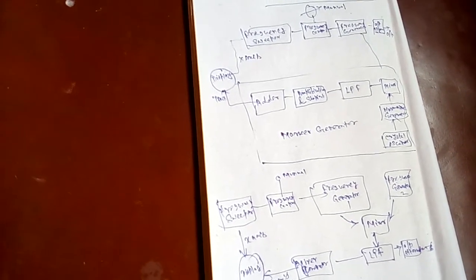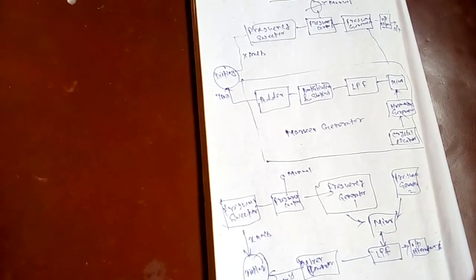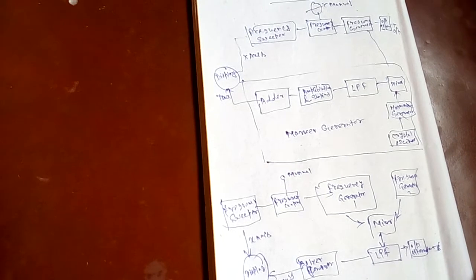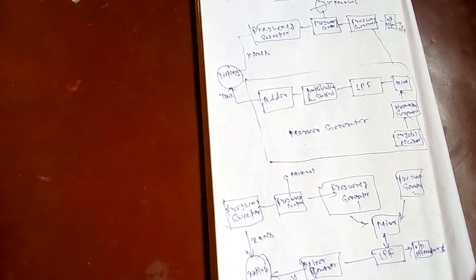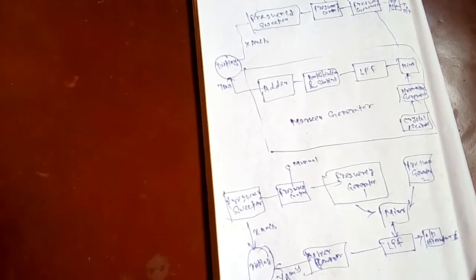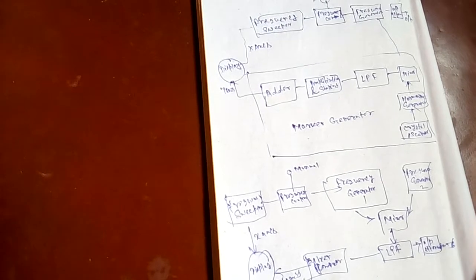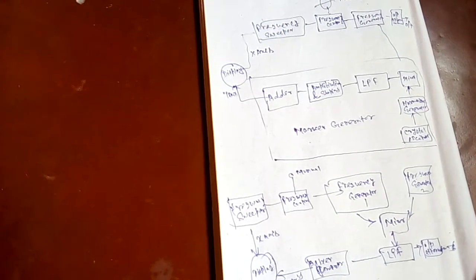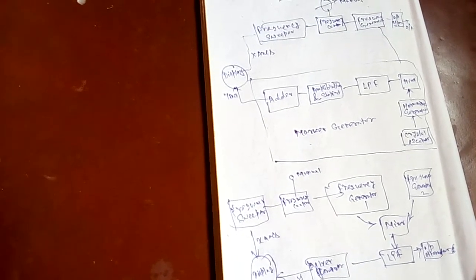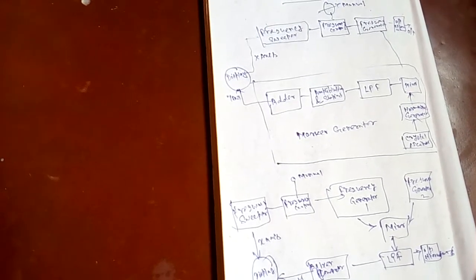This is compared with a signal corresponding to the required amplitude, and the error is fed back to the electronic attenuator circuit to keep the output constant. The graticule of the display is not accurate enough to interpret the frequency being displayed, so some sweep frequency generators have the facility of putting a series of accurately known frequency markers on the screen.